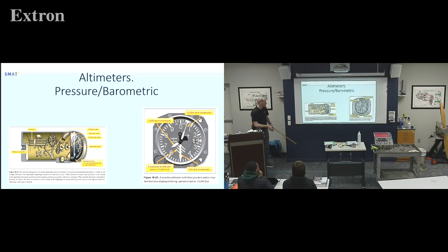All right, inside your altimeter you have what we're going to call a diaphragm or a bellows. Bellows, because there are multiple diaphragms, I guess is how you want to phrase that. Technically we're going to call them aneroids because they're a vacuum for reference.